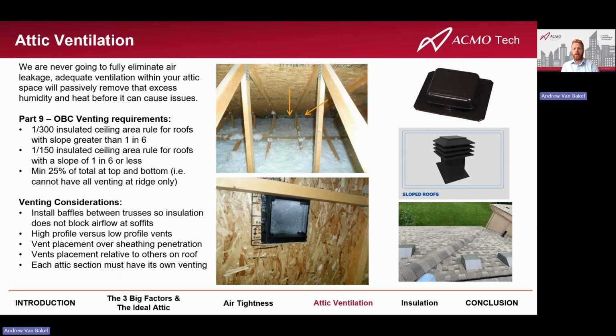Your vents at the ridge, there's strip vents, there's low profile, there's high profile. You want to make sure those are adequately sized for the amount of ventilation you need. And low profile ones can get blocked by snow as well, so something to consider. Placement of your vents: you want to make sure it's properly situated over the actual hole in the sheathing. Otherwise, it's not going to work to its full capacity.